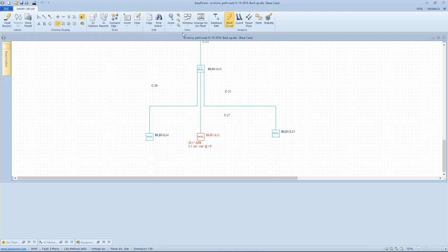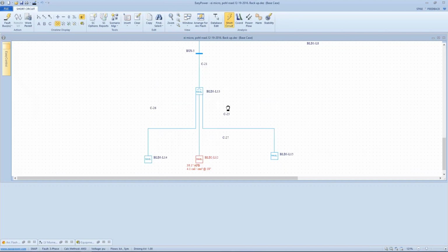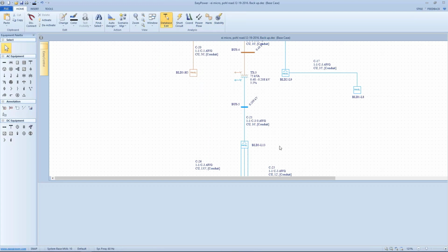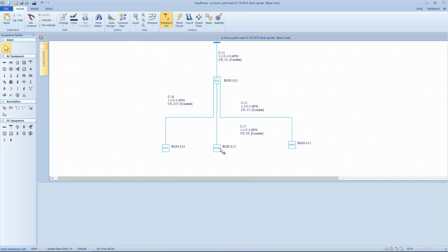Now this brings up another question. What is company policy? The standard says these systems, because this is supplied by less than a 125 kVA transformer and it's 208 volts, the IEEE 1584 says this is negligible, which relates to an incident energy of less than 1.2 calories, which again reflects the fact that the calculations going on are considerably conservative.